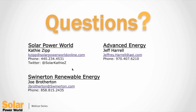One of the things we build into our selection criteria is we don't want our client to ever have to plan on replacing central inverters either. So this notion of, at year 11 we're replacing every inverter, we don't like that approach. We like that central inverters are almost like your car. You do oil changes, you have major tune-ups that are required, and ideally if you're doing everything you're supposed to be doing, they run for as long as we need them to, or at least within the design of the inverter we select.